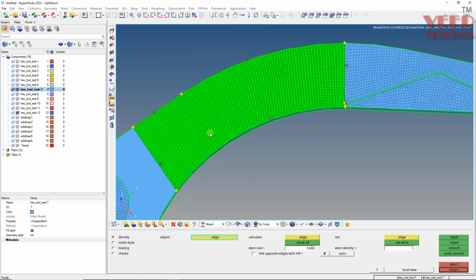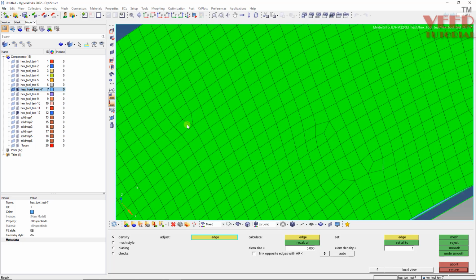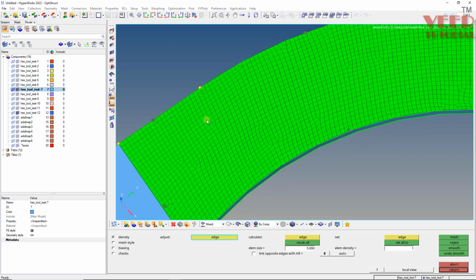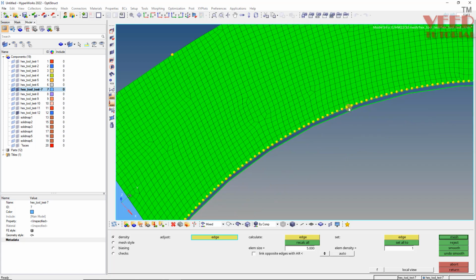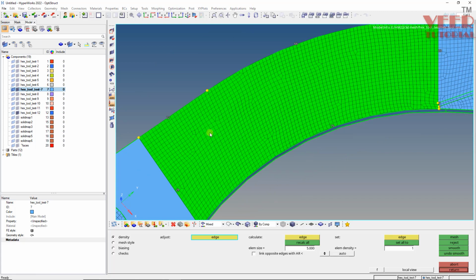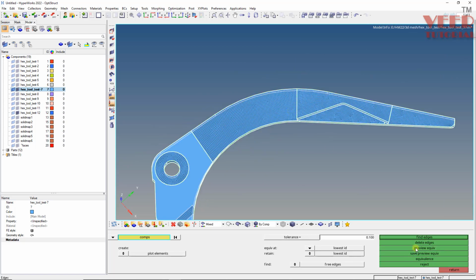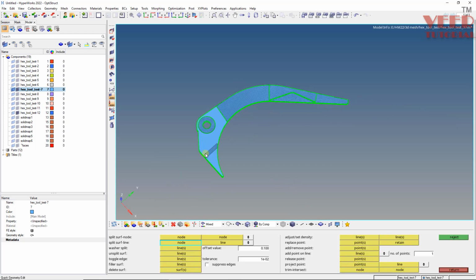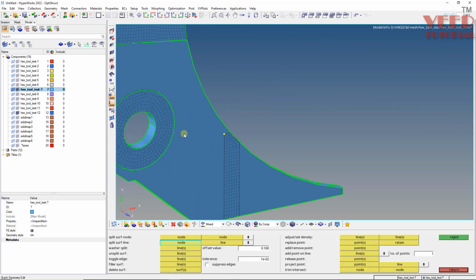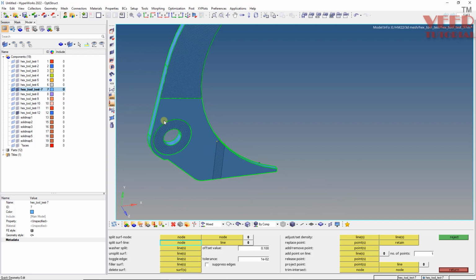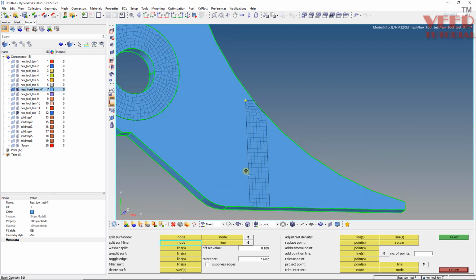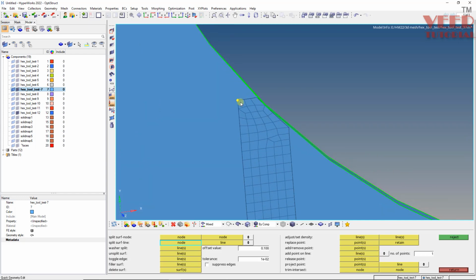We will have a tria here. This is, you can see, a tria. To remove this, let's say I will make it below 75. Now there will be no tria. Okay, now equivalence, and equivalence. Now only this bottom part is remaining. And for this mesh, we will also have to split this.